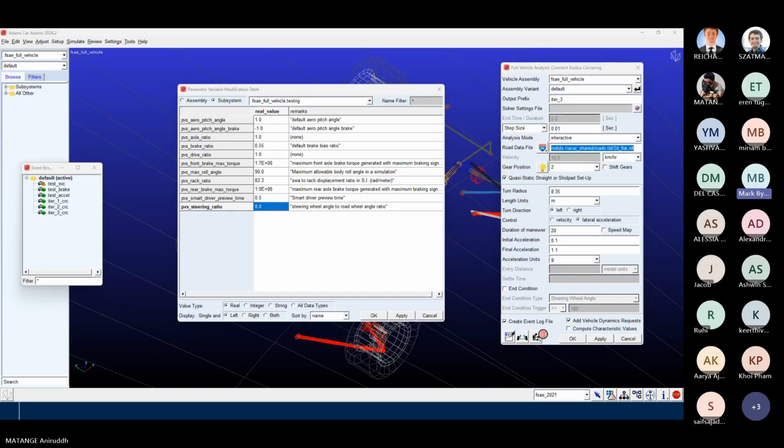So I think our team had problems previously because our suspension's inboard, and there were problems with modeling that. So I'm not sure it works, like the rocker tubes are shared between the roll spring and the heave spring, and the roll spring only ever acts in compression, rather than, if you've seen the Multimatic ones for FS, they act in compression and extension. So I think they're easier to model, but I haven't had a look at it myself.